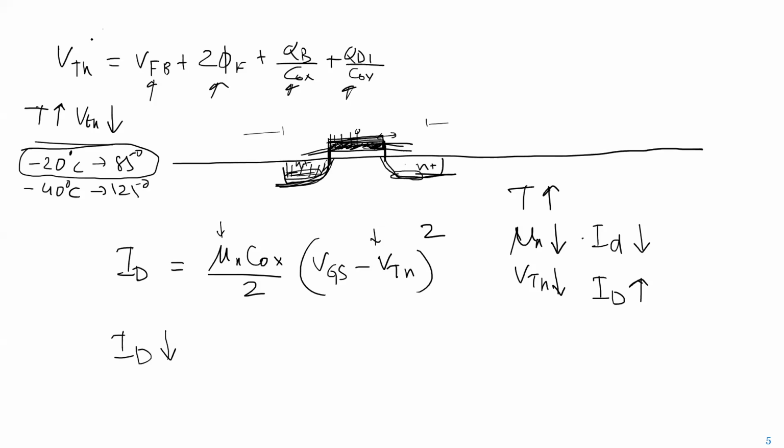We can't control the VTN. We can't say for different temperature, I'll control the VTN and make it constant. We can't do that. You can control other parameters to make it constant. For example, if you have a current going into some device and you want to make that constant with temperature, you can do that with circuit techniques, but you can't control the VTN because once it's given to you from the foundry, that's just given. You can't do anything with it. I don't know if that was the question or something else. So, Satabdi, was that the question? Yes, sir. Okay. All right, good. Any other question?